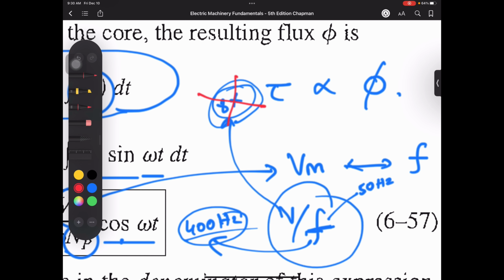So when you are going to have an increase in frequency, this is a very important point: you will not increase the voltage. Why? Because your machine is only designed for 230 volt. It cannot take that voltage. Unless and until your machine is designed for higher voltage, it has that insulation strength, then you can do it. But yes, when you are talking about a frequency decrease, then yes, you will do a voltage decrease.